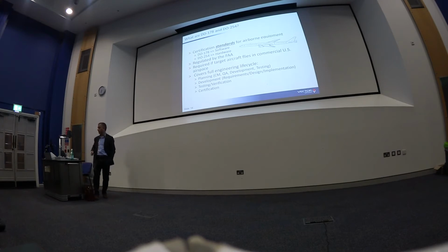One of the most common questions when a company asks us for consultancy, mentoring, tools, etc. for a new avionic project, and they don't come from avionics, maybe they come from another industry, is how difficult it is to write the software for the DO-178. The answer is no, it's not difficult, the development part, but the real effort is the verification. You spend much more time on verification activity than on development.